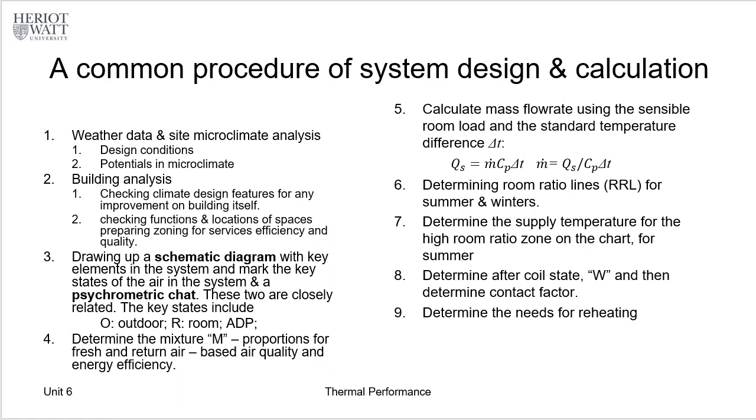Then we can go backwards to find out the after-coil state. Here we use W, and determine the contact factor of the heat exchanger or cooling coil.